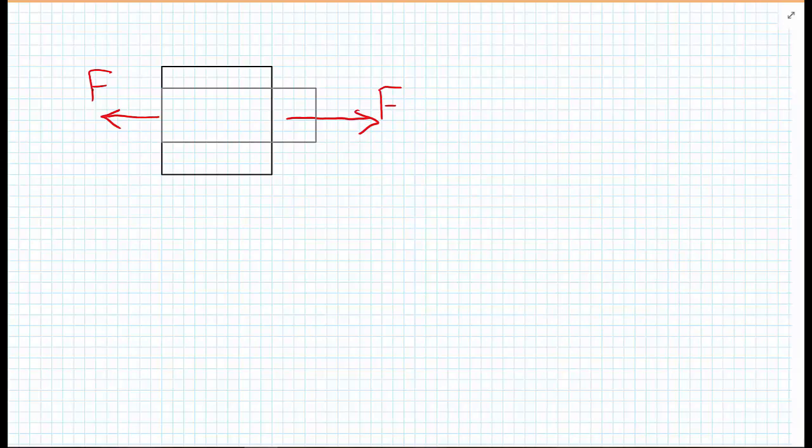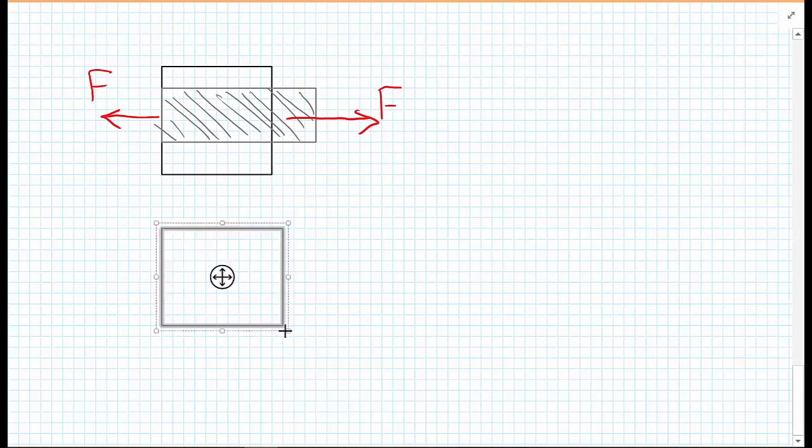But as a result of applying the forces now, we have a new shape of the body, a stretched body, and it's the action of the two forces at either end of the body that gives rise to an internal force in the body. And as we'll see in strength of materials, gives rise to stresses and strains in the body.